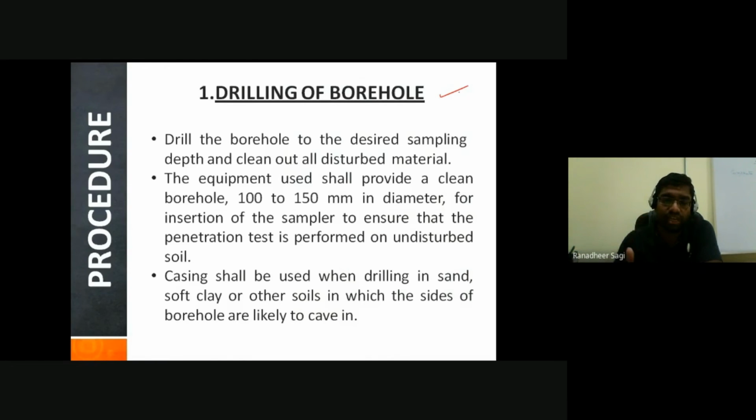So that's the reason why you should carry out your SPT test only at regular intervals of 1.5 to 2 meters. You cannot continuously get the SPT value of the soil throughout the depth. Only at regular depths only you will be able to get your SPT values.